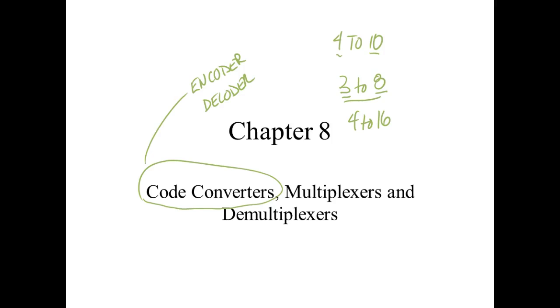So these are the primary ones we have. We don't have encoders to go from binary to ASCII and stuff like that. So basically we're going between the main numbering systems, right? Except for this one. This is not really a numbering system. This is BCD. So this would be 7442. This is the 74138, and then a 74154.